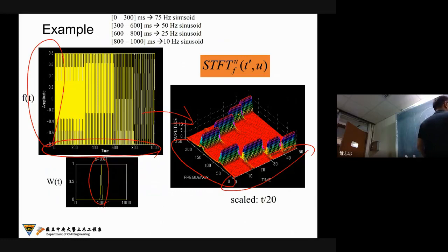Okay. So for this dT, you can determine the highest frequency, but actually you can find only half, right? This is because of the Nyquist frequency. But for this, you can find this is the T, and for the data, if you have a smaller length, it means that your resolution decreases in the frequency domain.